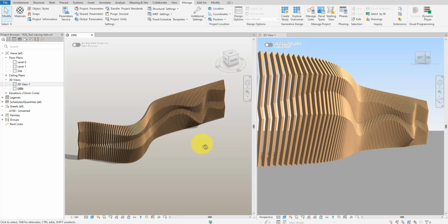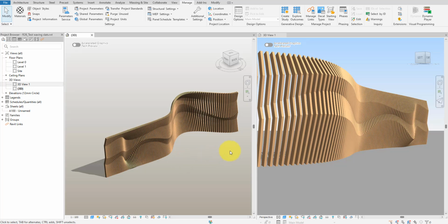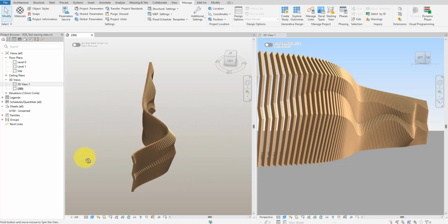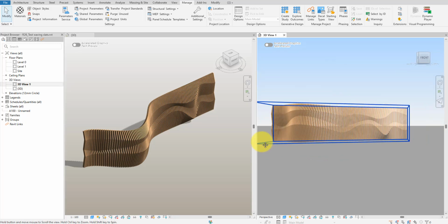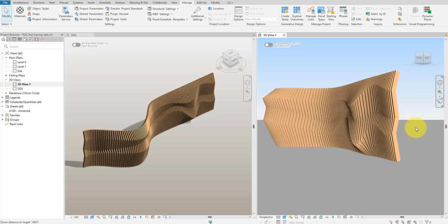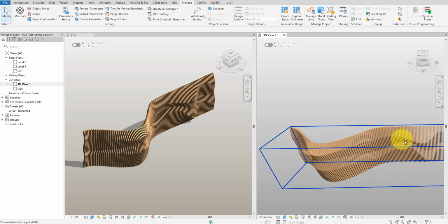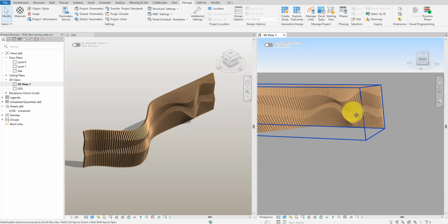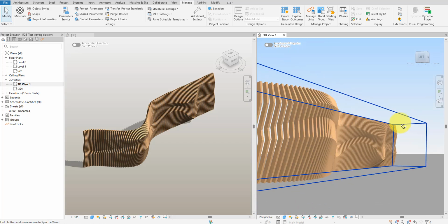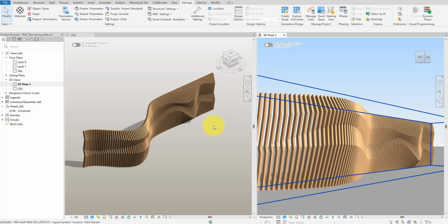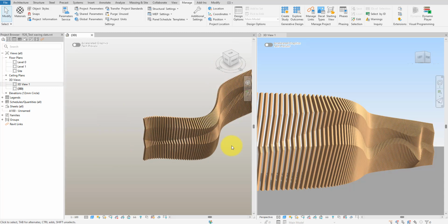Today, let's do some freeform modeling in Dynamo. I'll show you how to generate this type of design yourself. It can be a facade, a feature wall, or some fancy fence, entirely up to you. The script we create will be fully parametric, so you can adjust the size, thickness, and openness of all louvers in this system. If you don't have much time and just want to run this script right away, simply find in the video's description a link to download this script directly. If you, however, want to learn to code this yourself, let me show you how right now, step by step.